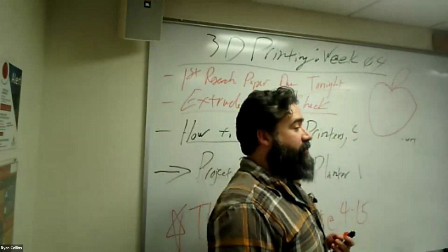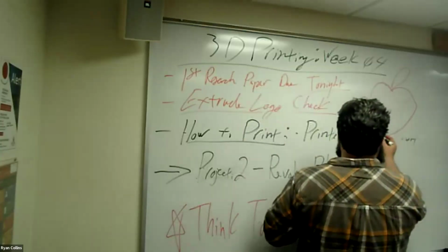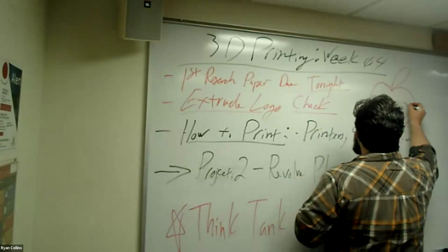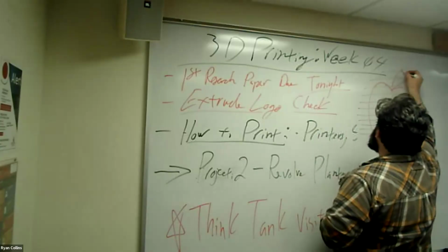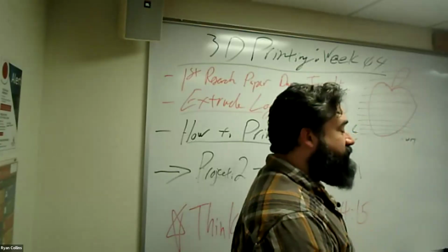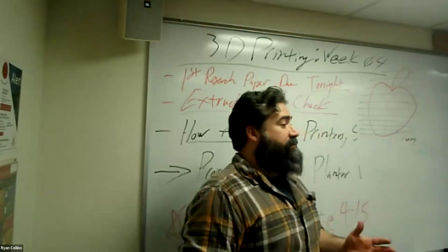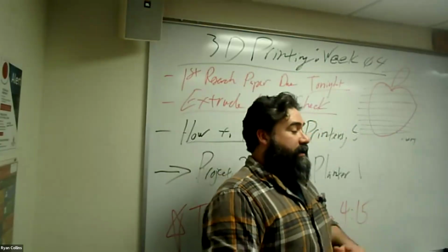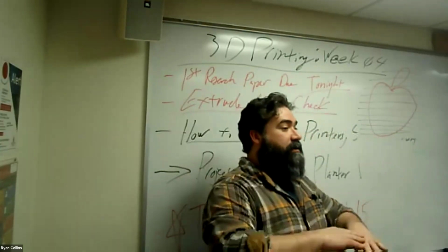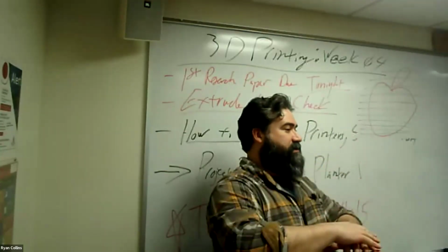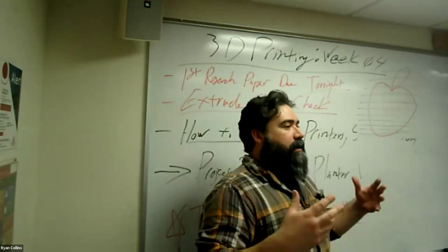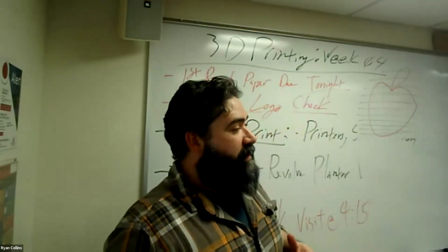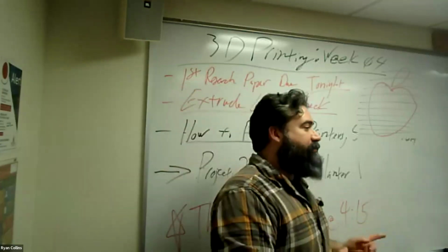And what a slicer program does is it literally takes that object and slices it into horizontal layers all the way up so that it can print. Because essentially, say you took an object somehow that was rendered in a regular paper printer, and you printed each one of these layers as a picture, and then you stacked all of those pictures on top of one another into a stack of paper. Ideally, that would create the same thing three-dimensionally. And that is how a slicer program tells a 3D printer to work.